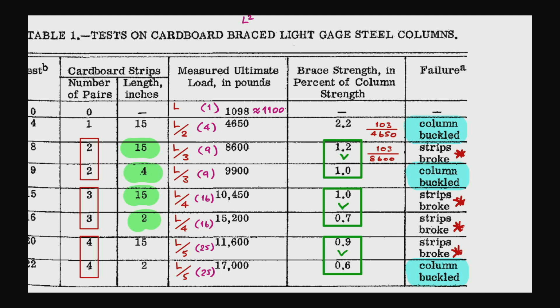And actually another reason why the cold form was used is because with a cold form cross section, the control of the dimension is easier. The tolerance of the dimension is less as it is cold formed, so it is easier to control, and it is easier to get pretty much the same geometry rather than using the hot roll steel cross section.